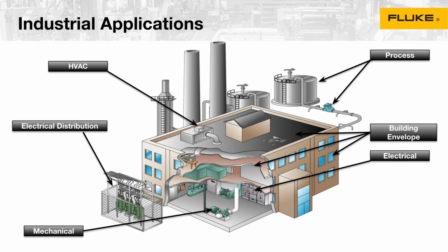The other aspect really is the building envelope. The building envelope could be a roof, windows, or walls. Often we take the example to our customers and say, sometimes you can look at a renovation or any kind of house. You can see if there's a cold spot in that wall. Maybe you don't have insulation, or maybe there's an issue right here. More and more, especially home inspectors and third-party contractors, are using this to enhance either some of the building construction they're doing, or simple inspections.